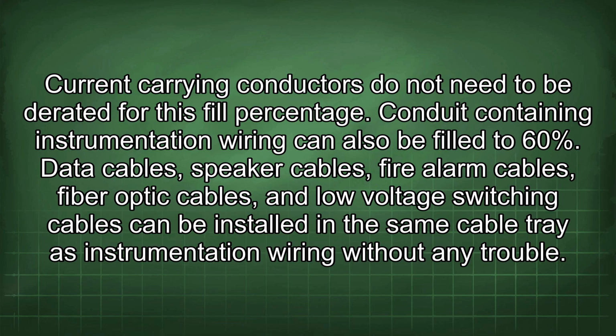Current carrying conductors do not need to be derated for this fill percentage. Conduit containing instrumentation wiring can also be filled to 60%. Data cables, speaker cables, fire alarm cables, fiber optic cables, and low voltage switching cables can be installed in the same cable tray as instrumentation wiring without any trouble.